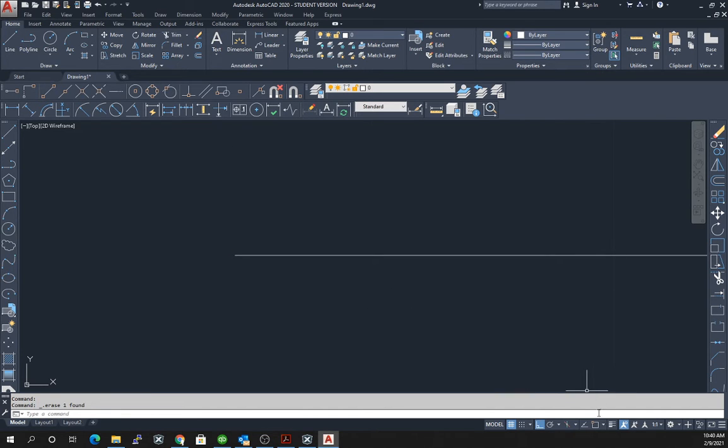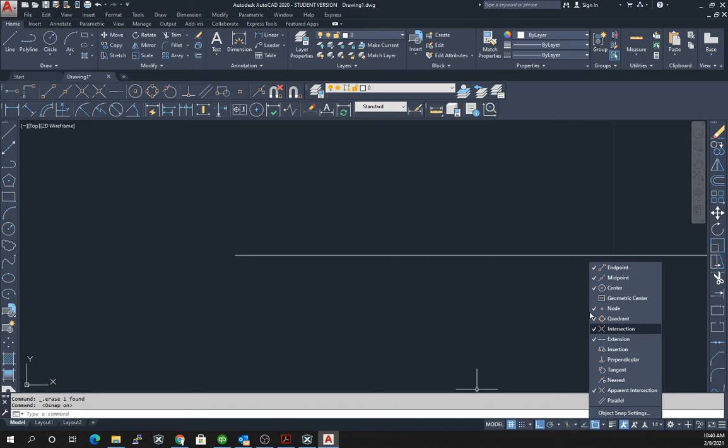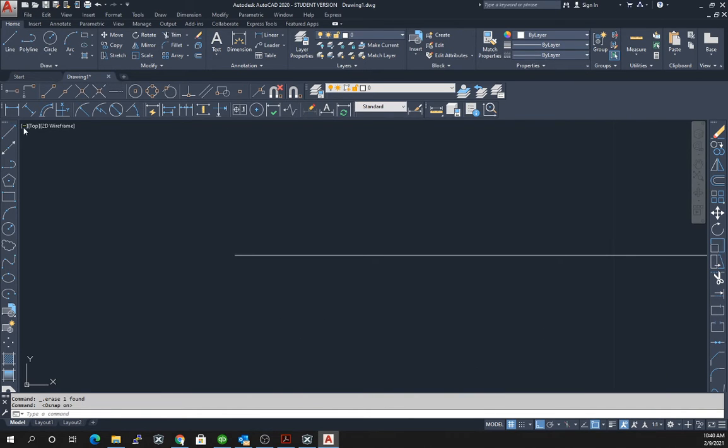But now if we turn on the Object Snap, and by the way, this arrow allows us to select right here what we want to be able to snap to. So if we need to quickly turn something on and off, we can do it directly here instead of going right into that drafting settings menu. Now once it's turned on, then when we come over here, we see the box light up. See this green box. And once we see that green box, we will actually start the line right at the end point of the previous line.